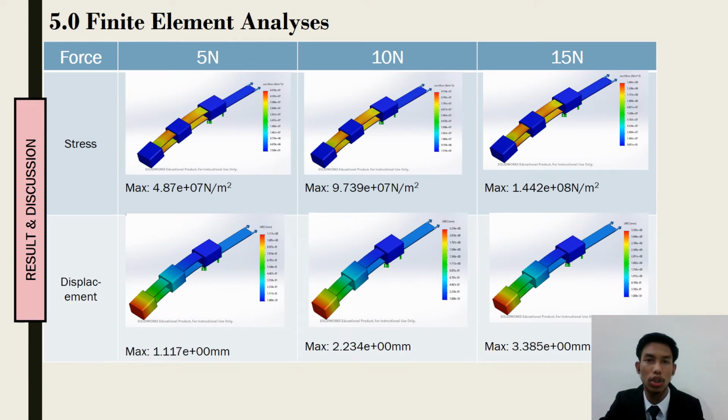In this slide, we show the finite element analysis on the index finger generated by the SolidWorks simulation study. In this analysis, we want to analyze stress and displacement for different forces applied. In observation, when the force increases, the stress and displacement also increase.